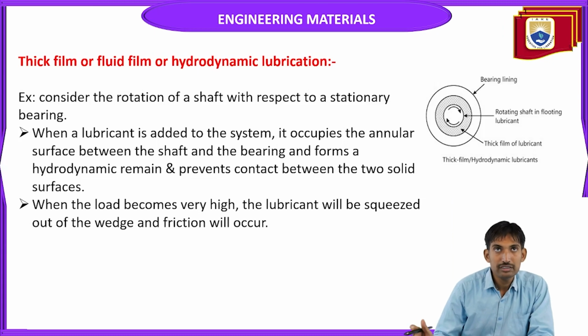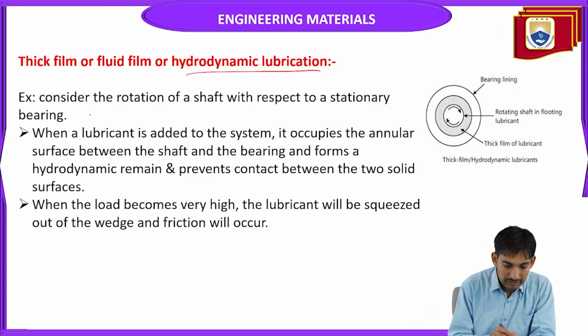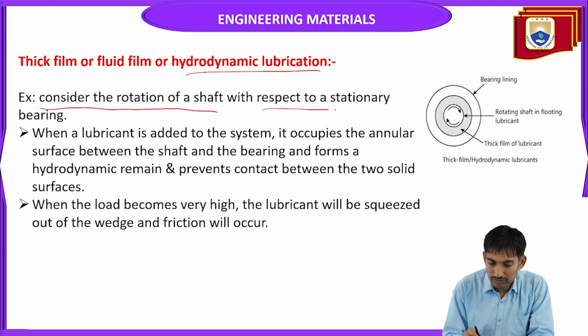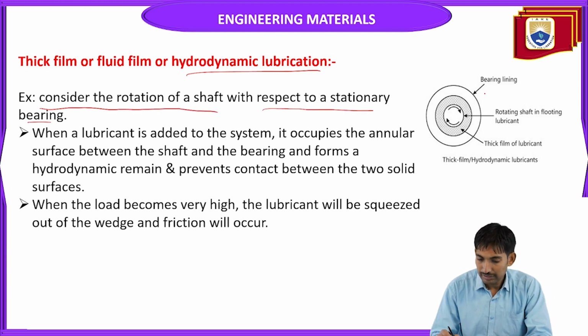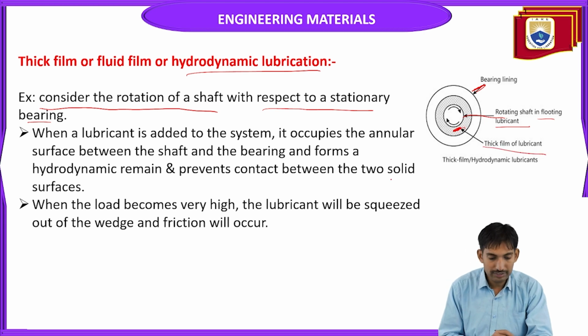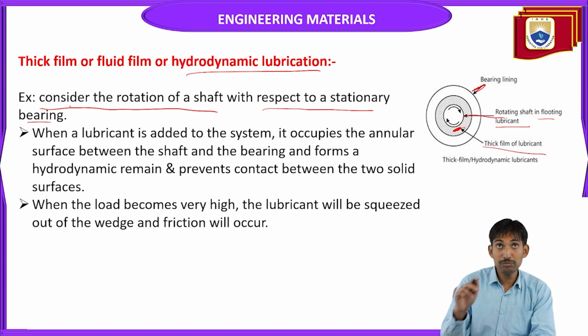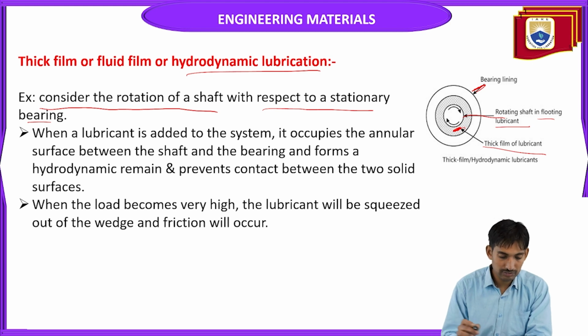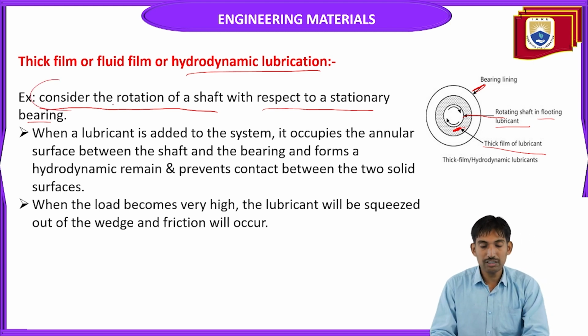The thick film or fluid film hydrodynamic lubrication. Example, consider the rotation of a shaft with respect to a stationary bearing. This is the bearing lining, and this is the rotating shaft floating in lubricant, and this is the lubricant oil, a thick film of lubricant.